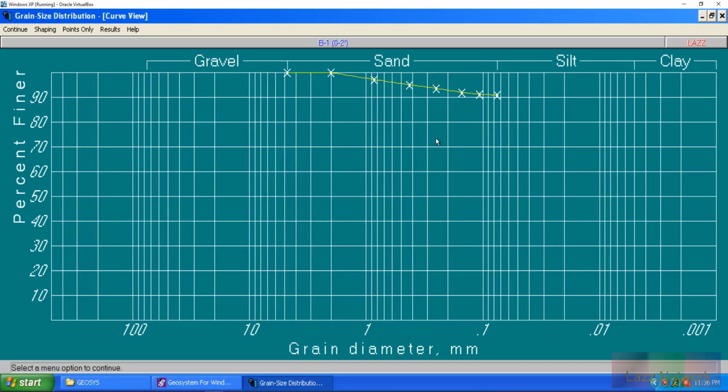I know that's an easy word to remember. So you would let it sit in that solution for 12 hours, and then you would start your test, putting it in your graduated cylinder, adding deionized water to it till you get up to your 1,000 mL mark, and then you'd start your hydrometer tests for the most part. I'm skipping a lot of steps here to simplify this, by the way.